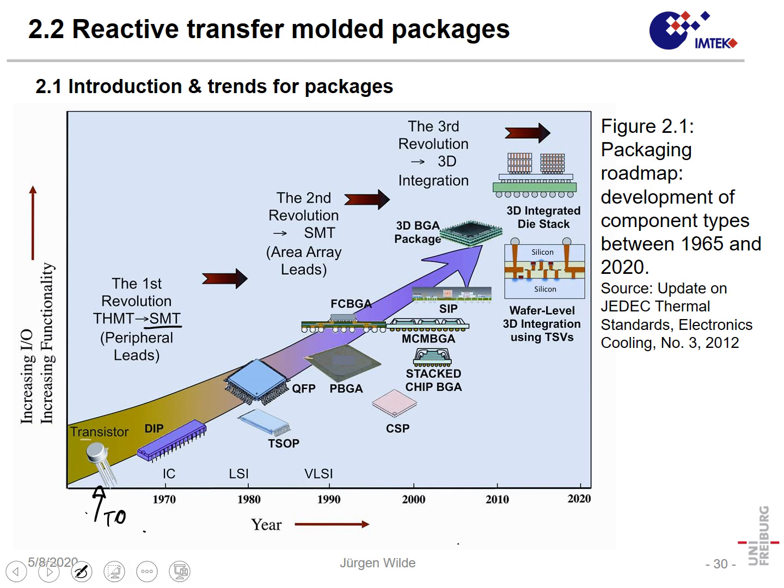What we have here is, for instance, a multi-chip module, BGA in that case. The individual chips are interconnected by wire bonding. We also found, after the year 2000, stacked chip BGA, so that means chips on top of each other, but the restriction here was that the higher chip must be smaller than the lower chip.